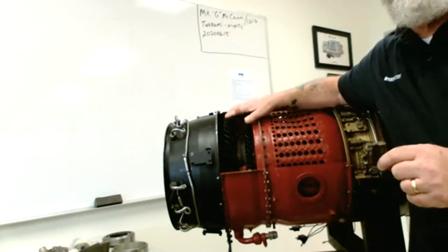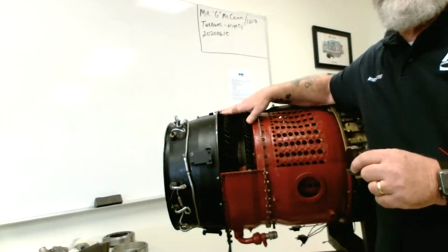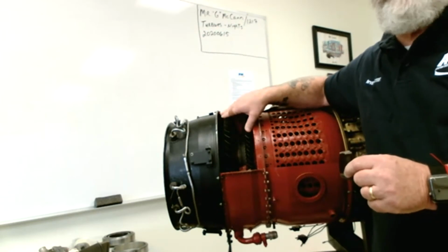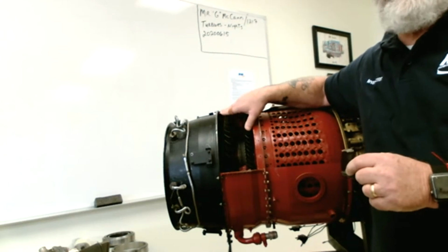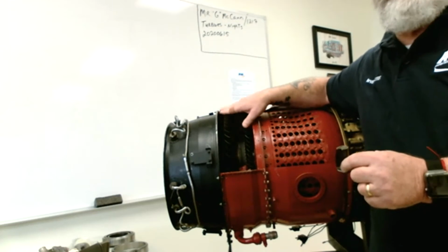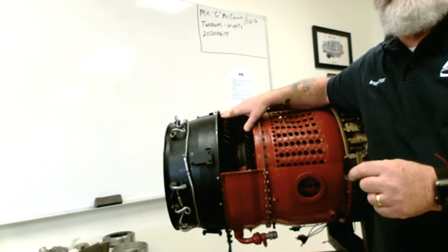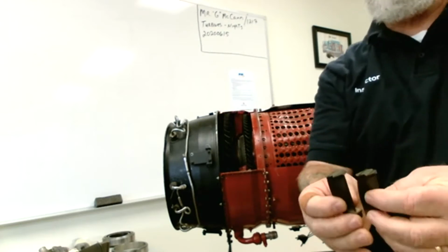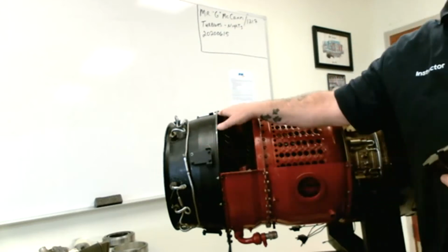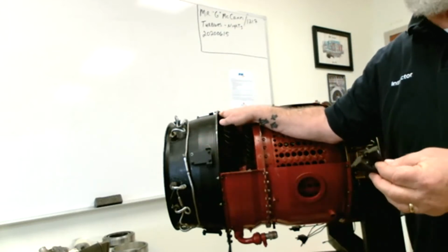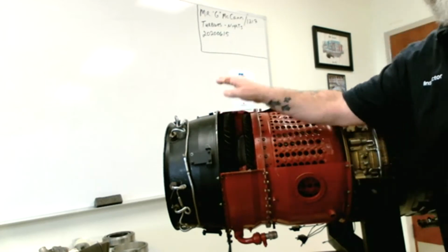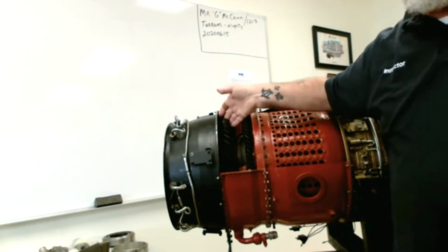So, when this engine is on the drawing board and is being designed, turbine blades that have an open tip might be utilized in a turbine that runs at higher RPM. Now, all turbines run at a high RPM, but just to throw some numbers out here, these open tips might be quite suitable for a turbine that's running at, say, 45,000 RPM. And if they decide to go with a shrouded type of blade, then because of the extra weight here, they would use this on an engine that was designed to run at a slightly lower RPM, let's say 30 or 35,000 RPM.